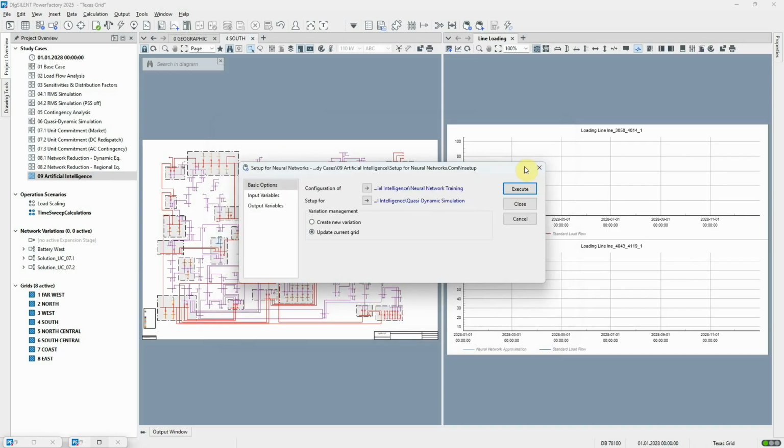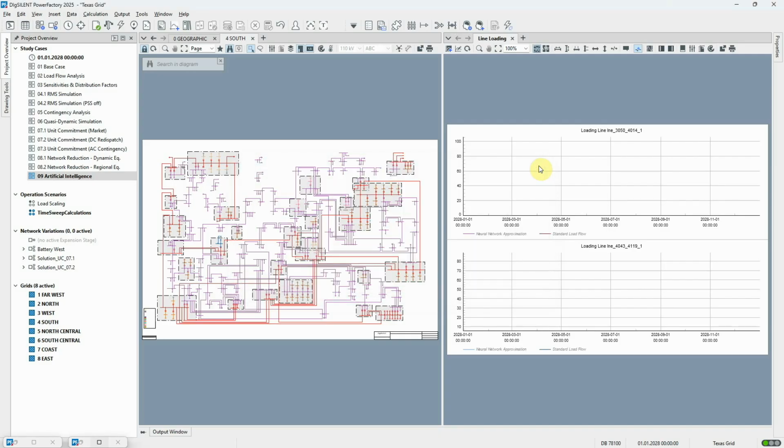A neural network is trained using a training dataset for which distributions are required as inputs. These can simply be defined by the user. But this command makes it possible to automatically generate the distributions from existing time characteristics. When the command is executed, the parameter distributions are created together with estimated correlations. The command has already been executed in this project, so the distributions and correlations have been created.